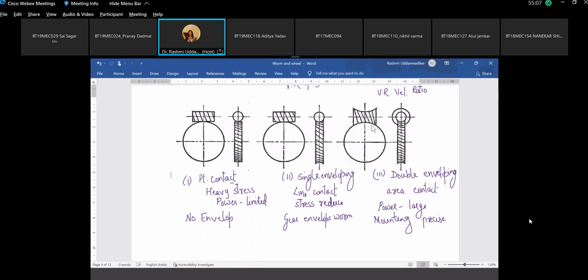So it would rarely be a situation where, like in spur gear or in helical gear or belt drive, you get worm from one supplier and wheel from another supplier and assemble. That is never done. So worm and worm wheel will always come together in an assembly, so that the center distance, the curvature for this enveloping is already done, checked, tested at the manufacturer, because this requires very precise mounting. So it's manufacture and assembly. This is really a challenge. Assembly is difficult.